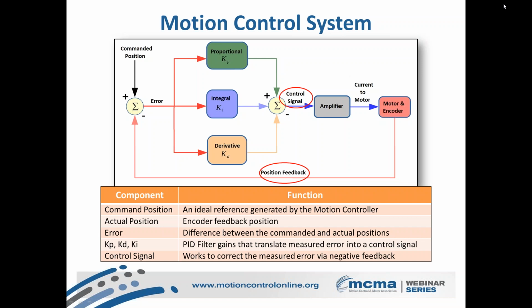On the other side of it, we have digital control schemes. There are varying protocols: TCP/IP, RS-485, Modbus, DeviceNet, and EtherCAT. One of the main benefits is that communication over Ethernet has become fast enough, over 100 megabit per second now, to make these types of communication what we call virtually deterministic, meaning that for all intents and purposes, you can ignore the communication latency in most applications.